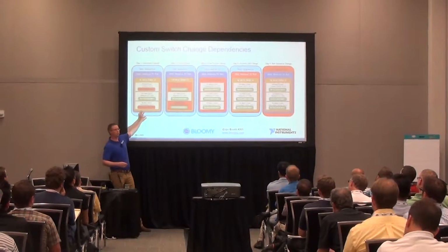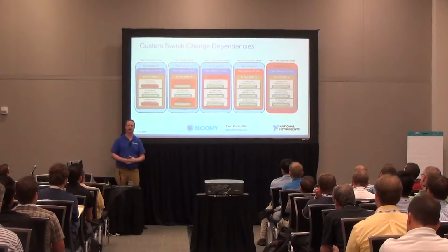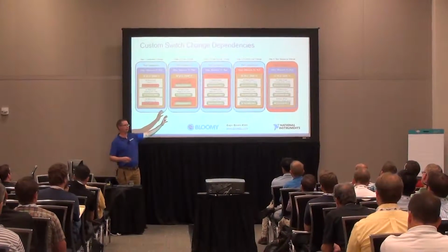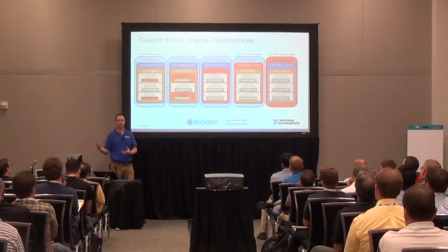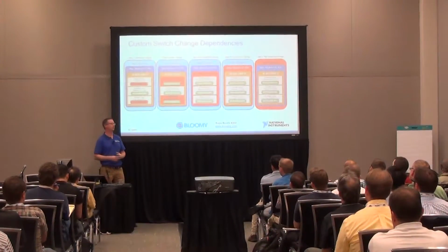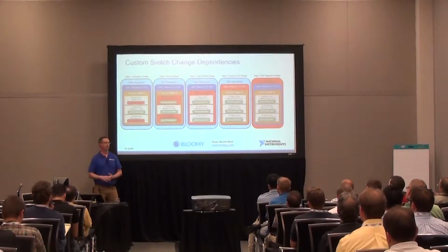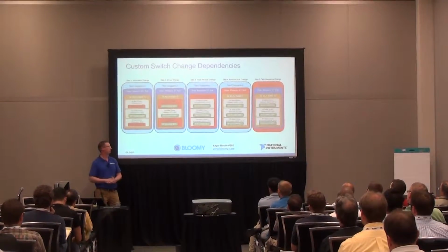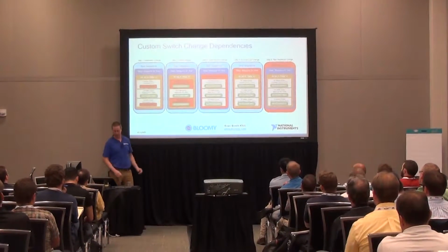So one small change on instrumentation has this really long-term effect of changing everything down the line to your test sequence. And depending on whether you're using a universal style test system, you may have a dozen or 100 sequences that are using that instrumentation, so now you have to change all of those. That could become weeks of effort just because you needed to extend your switch matrix a little bit.